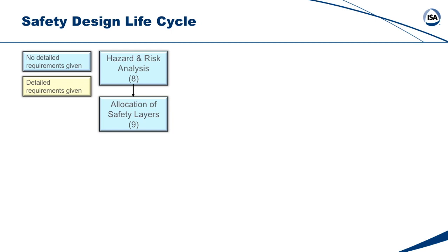Where can we use relief devices, scrubbers and flares and containment areas and alarms and fire and gas and everything else? So here we determine, okay, well, we do need some safety instrumented functions, and we determine the SIL, the safety integrity level that each safety instrumented function needs to meet, which I'll get into more in an upcoming slide.